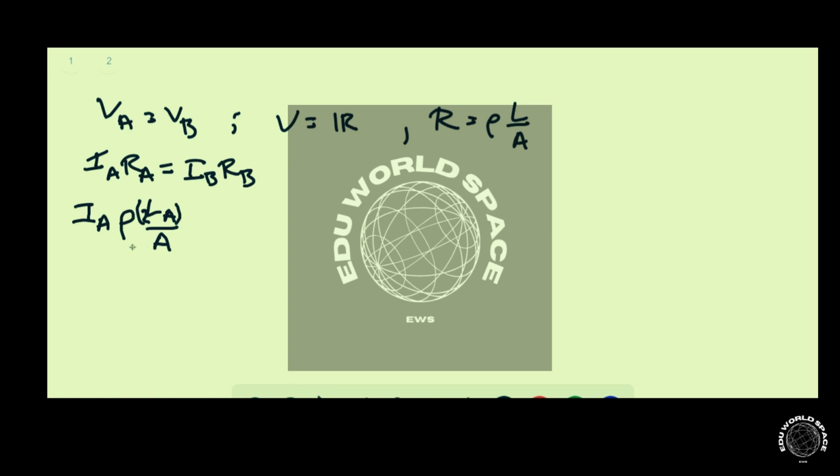So let's leave that as A, which is equal to IB times 2LB over A times rho. And it's all copper, so the resistivity is the same, the area is the same, and all of that cancels out, and the twos also cancel out, so we're left with IA LA is equal to IB LB.